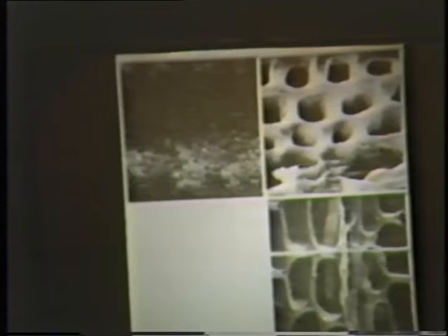We can get it either by making an X-ray map. Here is a piece of wood that has been impregnated with a copper preservative, and here is an X-ray map. You would say simply there are more copper X-rays in this region and less copper X-rays in that region. That's all you can say. Or you can run a line scan across the surface, and in this particular region, this again was for copper, it goes up, indicating there are more X-rays. All you can say with this type of qualitative analysis is that there are more X-rays, or less X-rays. The next one, please.